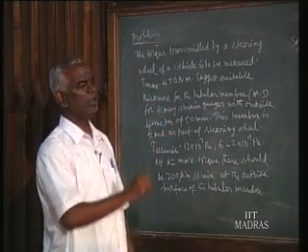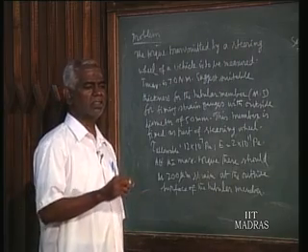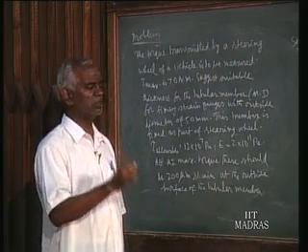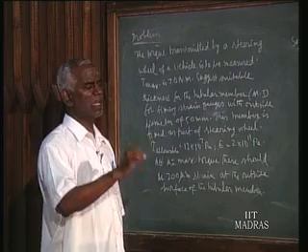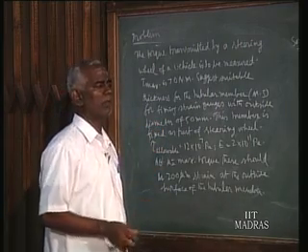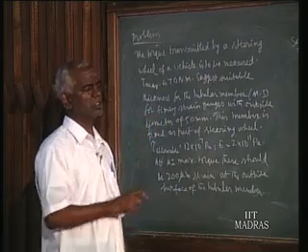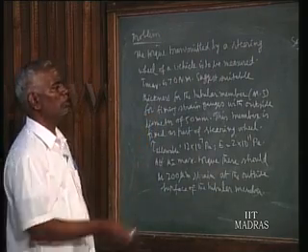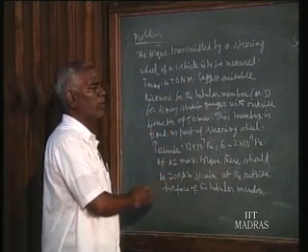If you go for a solid shaft, then it will be a very small diameter to produce sufficient strain, and in a small shaft you cannot paste the strain gauge. That is the problem. To avoid it, we go for the tubular member. It will be weak, at the same time we have got sufficient area. So to illustrate that, we have worked out one problem here.